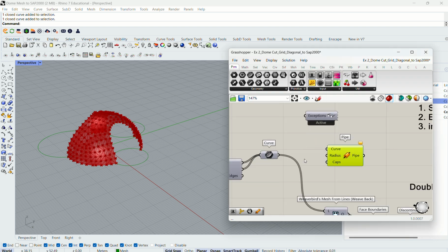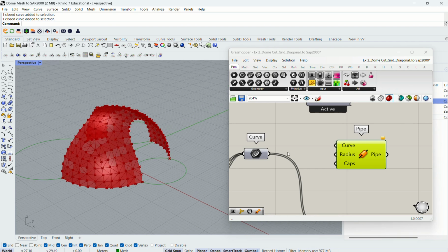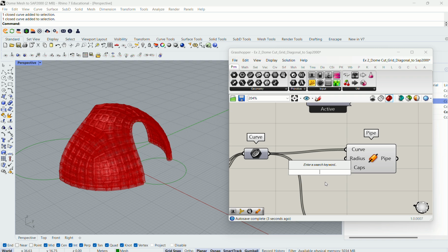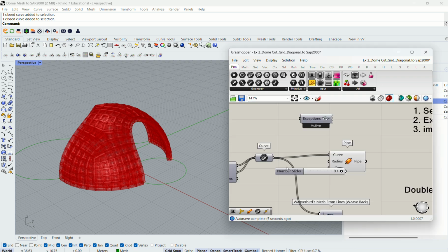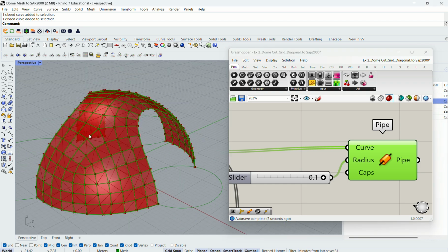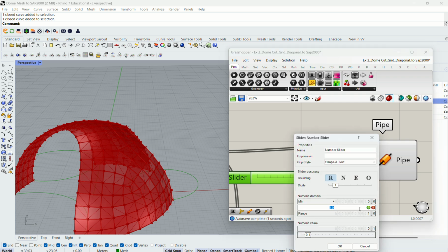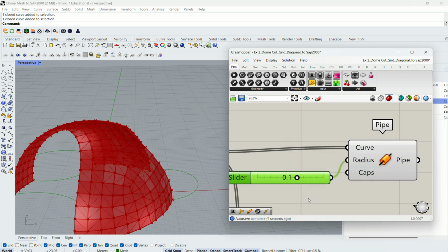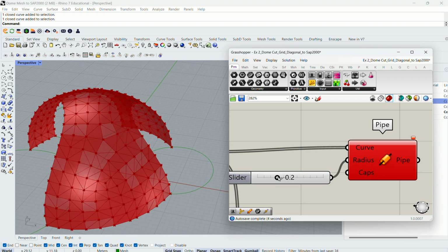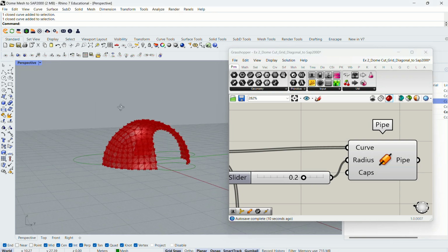Let me give you another interesting element, because during the design phase, maybe design teams want to see overall images. So this is in meters, and I'm going to assign some member extrusion, right? Maybe I'll make it a little bit bigger, 0.25. So if we use pipe, the pipe structure looks like this, right?